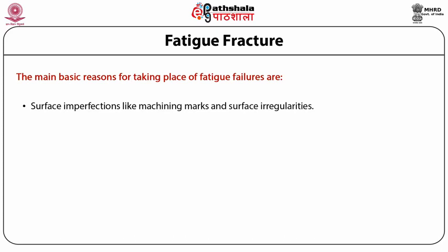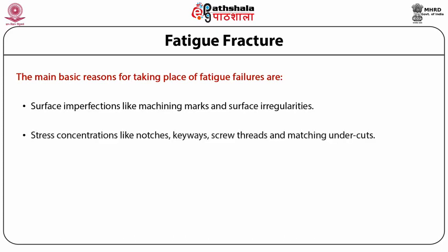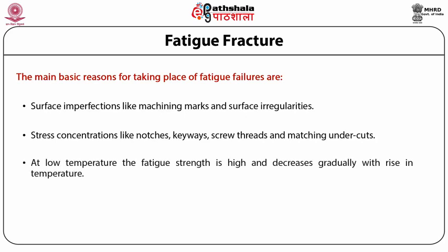The second reason is stress concentrations like notches, keyways, screw threads, and machining undercuts. The third basic reason is that at low temperature, the fatigue strength is high and decreases gradually with rise in temperature.